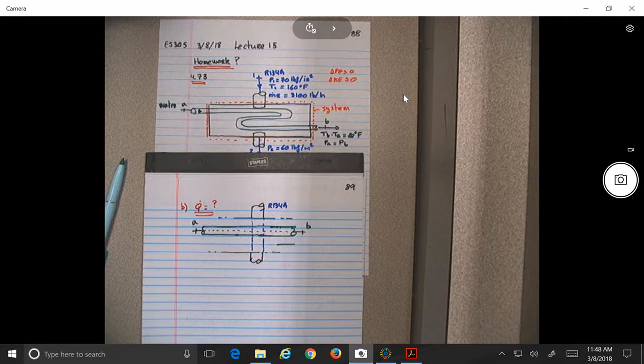All right? So then for the water to gain heat, what needs to happen to the refrigerant? I think this is something strange because the function of the refrigerant generally is to remove heat, no? Okay. But look in this case that this refrigerant is used to add heat. So what's going to happen? The amount of heat gained by one is the amount of the heat that is being lost by the other component.